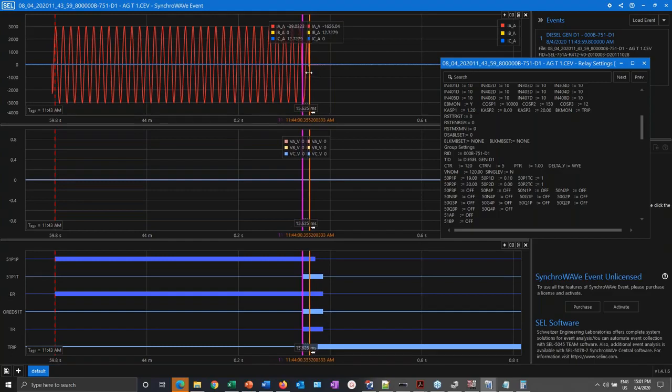But that still doesn't account for the rest of that time. My educated guess in this case is that the relay has an electromechanical relay on the output that has a bit of time to act, and when you put those two times together, you get a difference in time that is, I would say, inevitable.